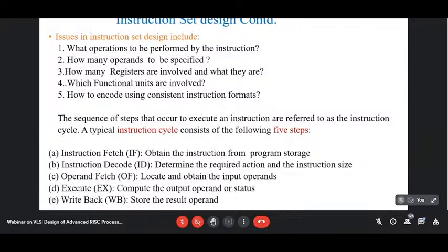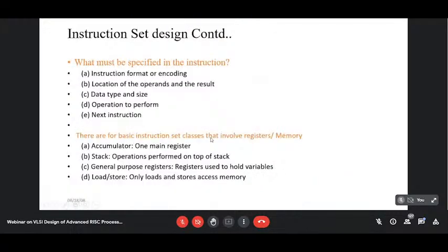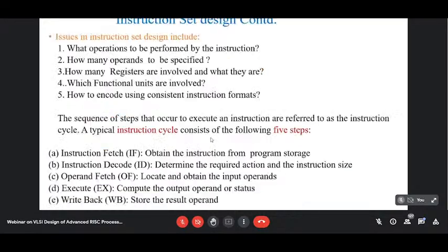First, when you deal with the von Neumann architecture, it is basically a store and forward concept. First the instructions are stored in the memory. From the memory, the instruction needs to be fetched onto the CPU. So there must be an interface between CPU and memory. Through the interface, from the memory, the instruction should be brought to the CPU.